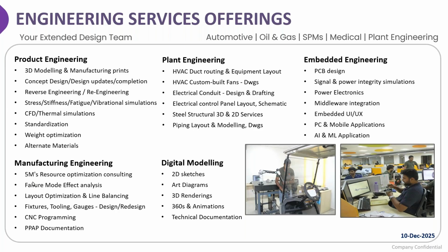We validate the design by performing FEA simulations, predicting strength, stiffness, fatigue, vibration, and impact resistance. We have the capability to do thermal and flow simulations also. We also support standardization of design variations and weight optimization using topology, size, and shape optimization, and material conversion projects such as iron to aluminum, and sheet metal to injection molded plastic parts.